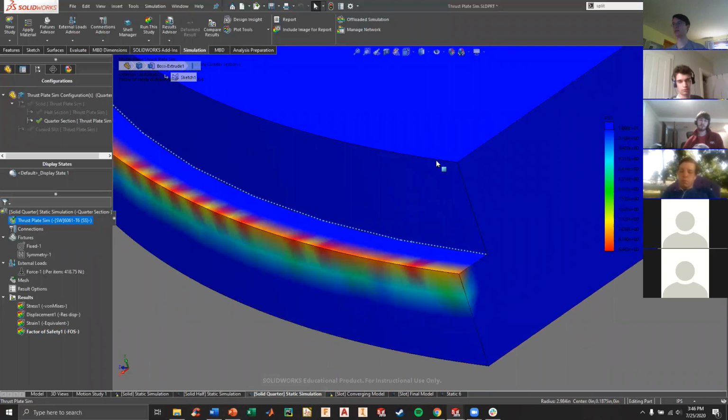Another option, like I said, is to run a nonlinear study where the stress cannot reach infinity because the material will plastically deform before that. So it will take into account that, and then you won't get the singularities in your model. And then another option is to just ignore it and say, I, the engineer, I'm looking at this, and I know that this result does not make any sense. So we're just going to ignore it. And that's actually what I've decided to do with this model.